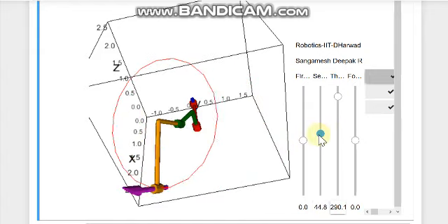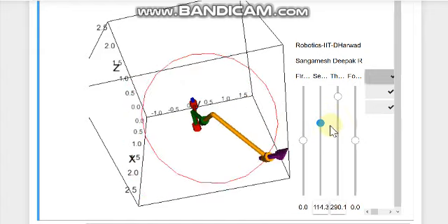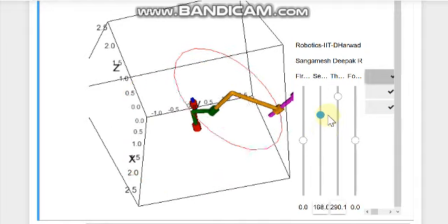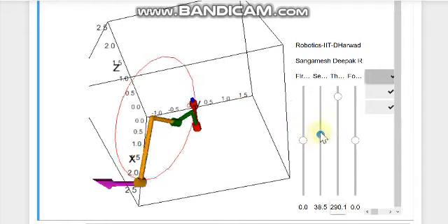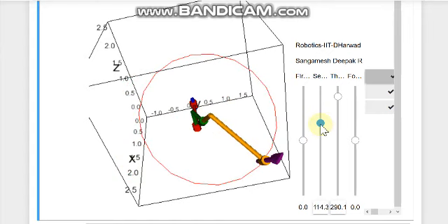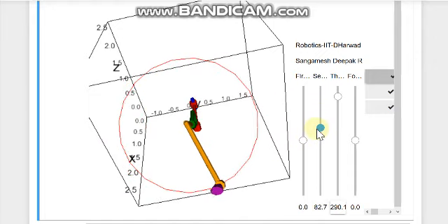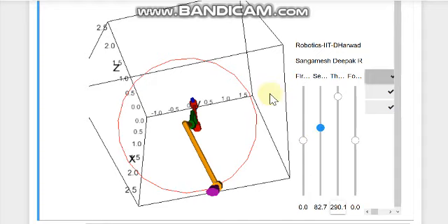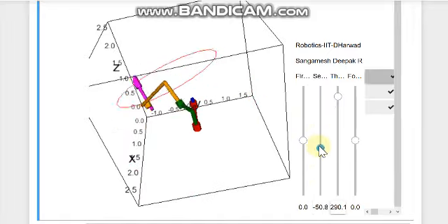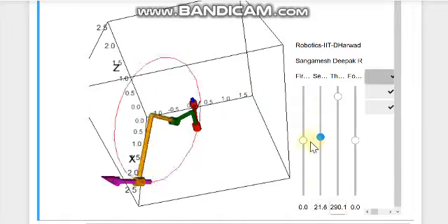So in the second stage, what we will do is we will change the value of theta 2, see the set of locations for this curve and collect all those locations and form the next stage, which we will call as theta 1 constant surface. You know that when a curve sweeps over some value, it typically gives a surface. So let us see, as I change theta 2, what surface is swept by the circle.